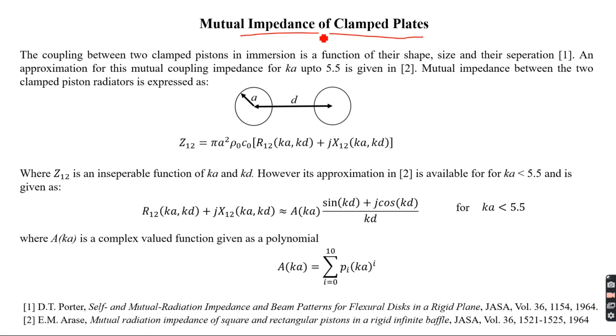They also tend to push one another, and that peculiar phenomenon is the mutual impedance. It is modeled by the mutual acoustic impedance. It's important to include the effect of the coupling because the cells in an array tend to push each other. If the separation is larger, you don't have much coupling between the cells.